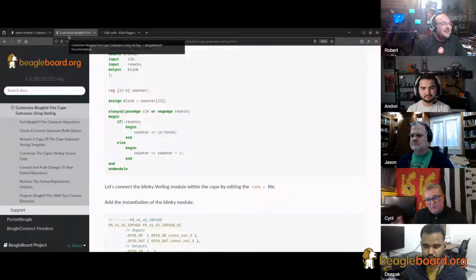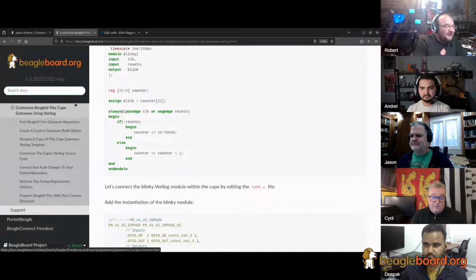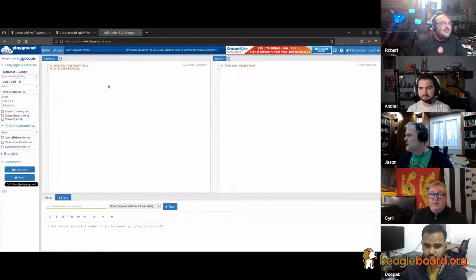It will try different patterns and go a little bit further, starting from that little example. But more importantly, it explains how to use Verilator and C++ to write a test bench for your Verilog, and that's really the key. The key thing that's not yet in that documentation, and in the Verilog template, is the C++ test bench template.